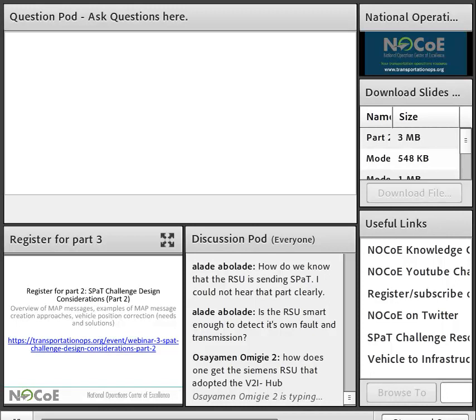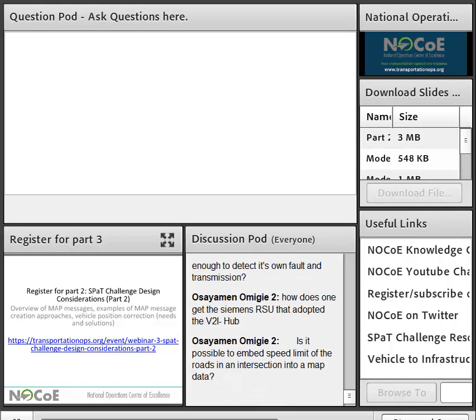Unfortunately, the handshake is also implementation specific. There are some vendors that believe, hey, I'm going to send the SPaT data to the RSU. If the RSU receives it in time, terrific. If it doesn't, well, in a tenth of a second, maybe I might resend it. So as long as I'm broadcasting it over UDP, I'm only interested in the latest one. I don't really care if you receive it or not, because I might send another one in the tenth of a second. Other vendors may say, no, I want the handshake. I want you to confirm back that, yes, I did receive it, so you can stop. Unfortunately, it could go both ways. It's how you implement it.